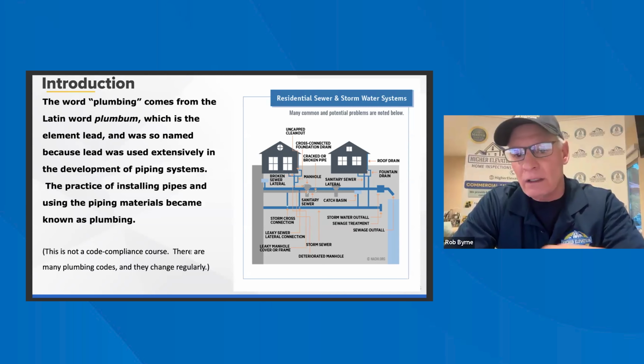Size of water supply pipes to fixtures. These are standards they go by. Sometimes they're bigger size pipes. Water closet flush valve. An important point on the bottom: if it's going through a manifold with individual distribution pipes, the flow can be reduced because it's going through there. Again, another bend and turn on the supply line.